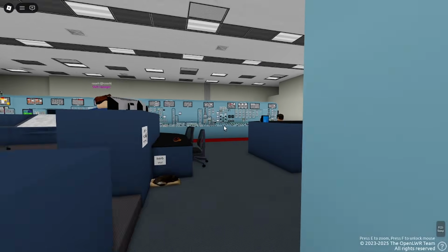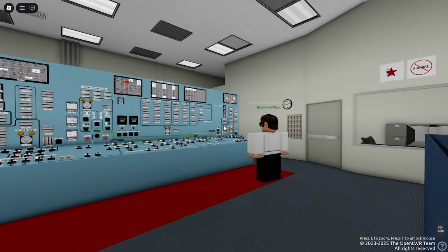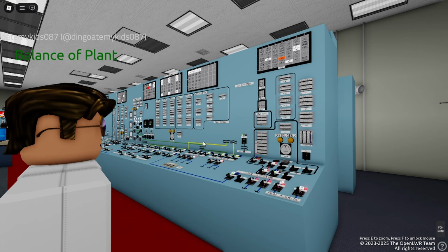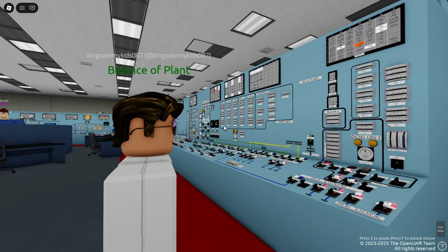As you can see, the operators are busy managing the situation. The plant has experienced an earthquake that caused electrical lines to fail. The plant is currently running on diesel generators, which are a backup power source. The reactor has failed to scram, with control rods staying outside the core, which means that the core is still critical. This condition is called an ATWS, Anticipated Transient Without a Scram.